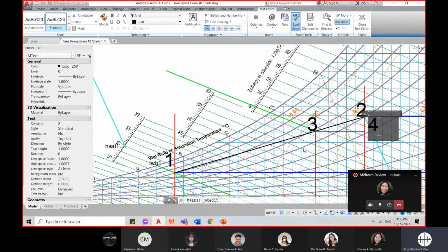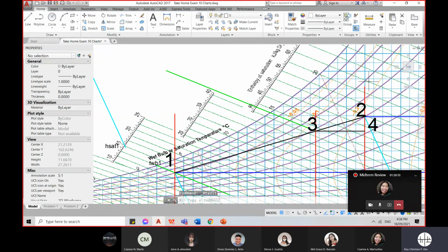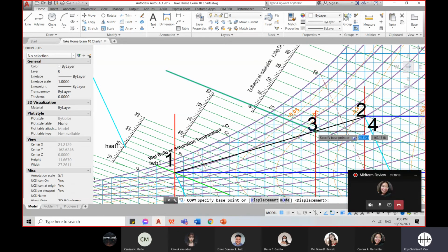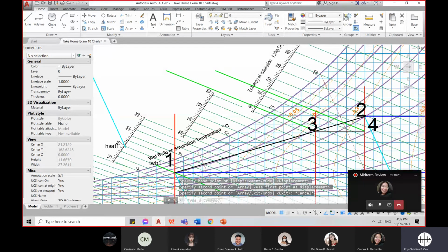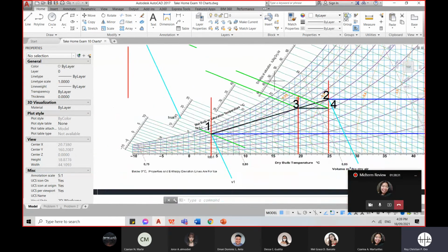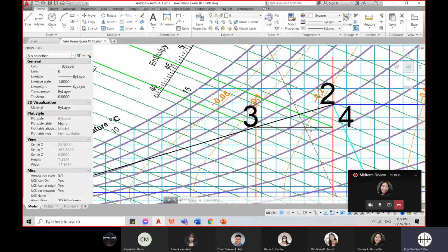And same as before, we get H4, since we need the enthalpy to do the energy balance to get the heating required. Same again, we follow the diagonal and then read the enthalpy. This one is between 45 and 46, so it's 46.5 at saturation. And since it is a bit far, I assumed the enthalpy deviation as 0.2.